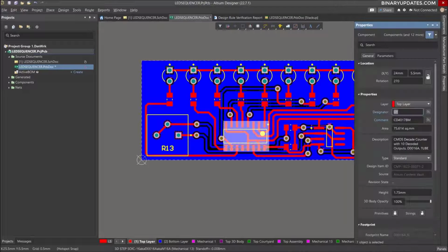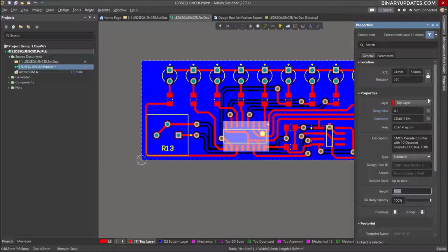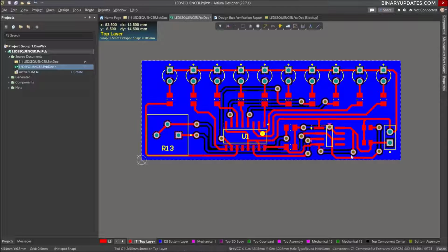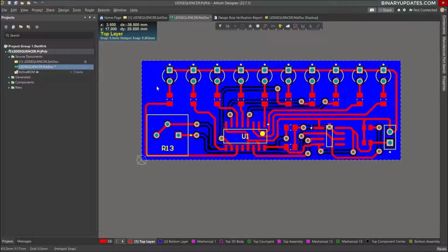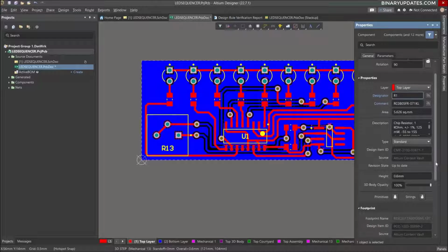So now I select this component here, U1 is the name of this component, and the height is 1 millimeter. I want to make it more meaningful, more visible, so 1 millimeter smaller looks better. And now you can see the name shows up. Something for these resistors is very important, because every resistor is connected to the LED here. So I select the resistor, and let me just check. Okay, just select the resistor, and I think all those resistors, make it visible.